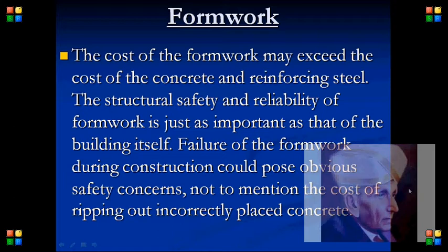Formwork. The cost of the formwork may exceed the cost of the concrete and reinforcing steel. The structural safety and reliability of formwork is just as important as that of the building itself. Failure of the formwork during construction could pose obvious safety concerns, not to mention the cost of ripping out incorrectly placed concrete.